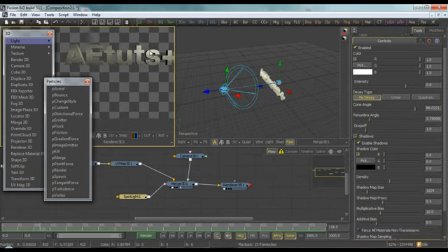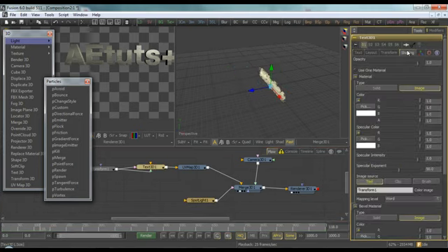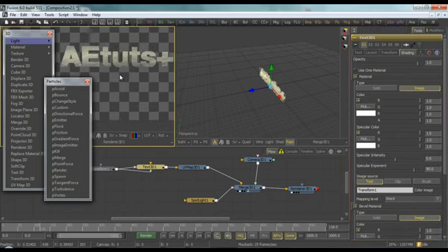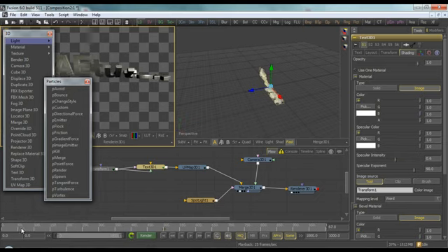One more thing, we have quite strong specular here, so let's set up specular intensity, which we can do here in shading. I will lower intensity to 0.6, and specular exponent to 90. Yeah, it softens up a little bit. We still have the shadows and everything, but I think it's much nicer right now.